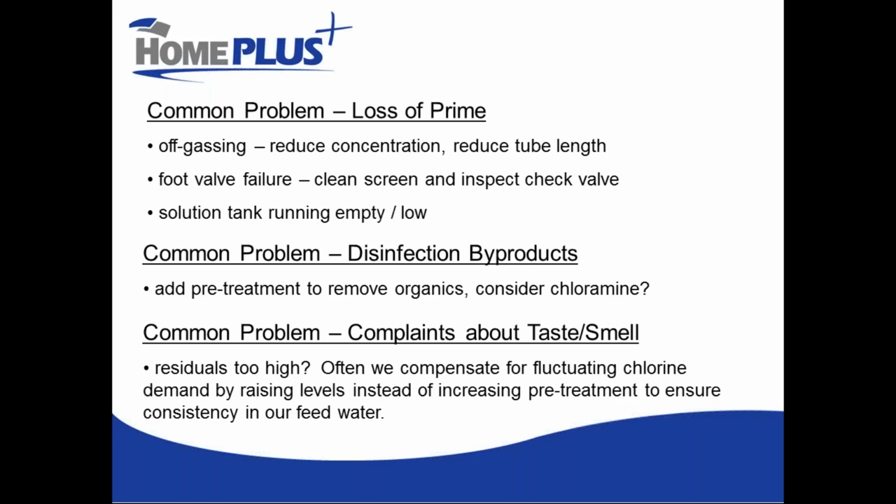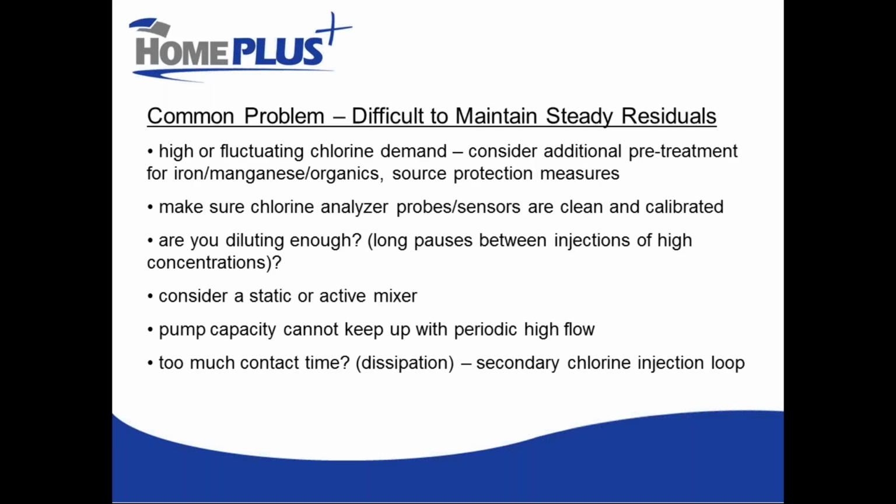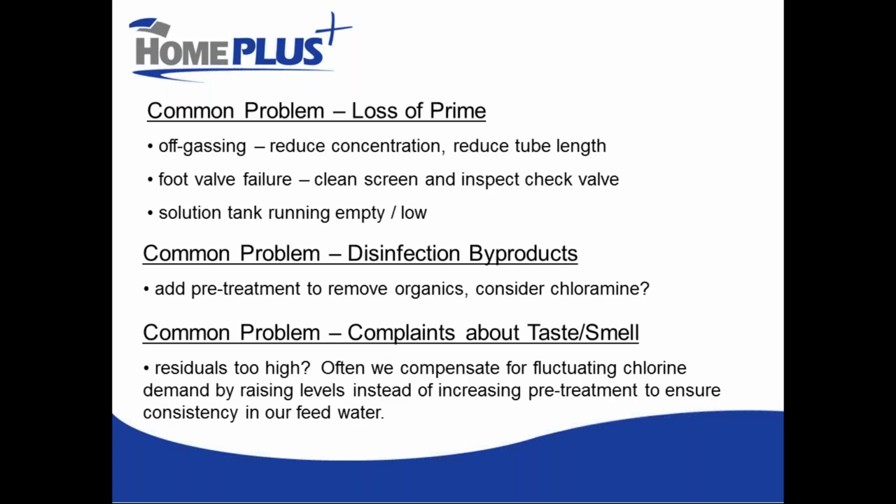Another problem you may deal with is complaints about taste and odor. And this can often occur as a result of our residuals being too high. This is not uncommon in a situation where we attempt to compensate for our fluctuating chlorine demand. So we have this problem here: we have difficulty maintaining steady residuals. So what we do is compensate by simply upping the chlorine that we're injecting. And at some point that comes with the consequence of affecting taste and odor.